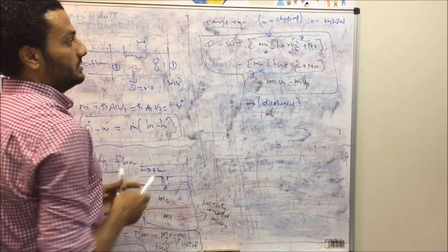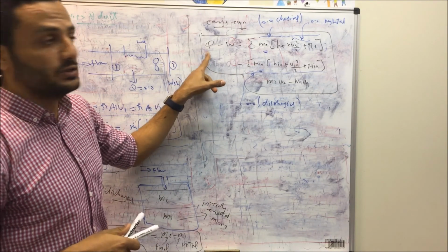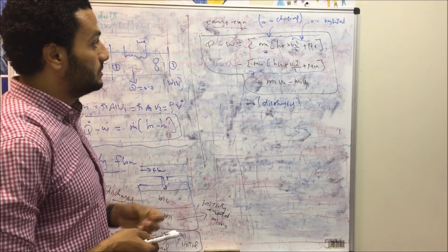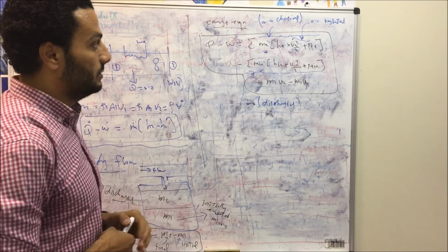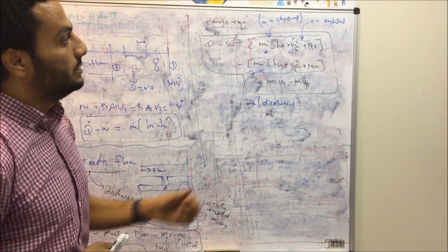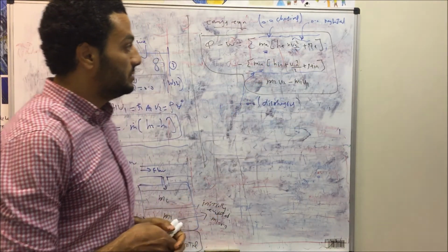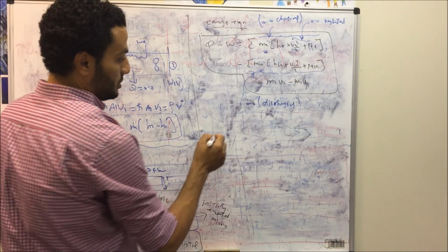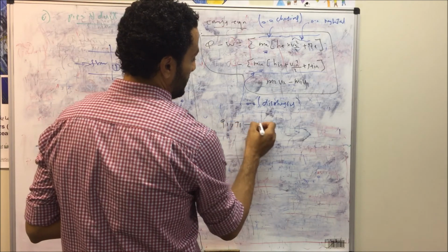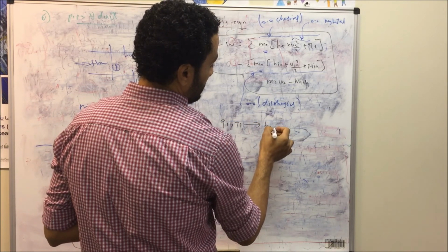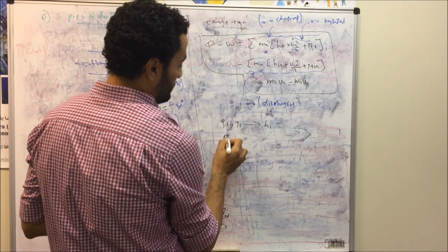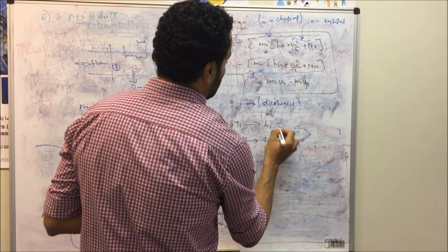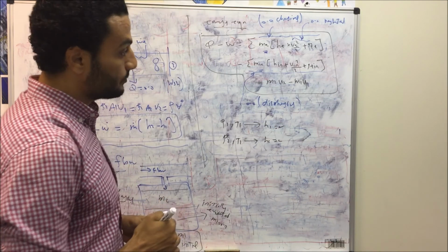Heat transfer and work are the same as before. You have to consider sign convention for heat transfer and work. If the system is adiabatic, heat transfer is equal to 0. If work is not given or required, in this case the work will be 0. The terms of kinetic and potential energy will be neglected. In this case, the initial condition P1, T1 will be given to you, then you can calculate H1. Given the final condition P2, T2, we can calculate H2.